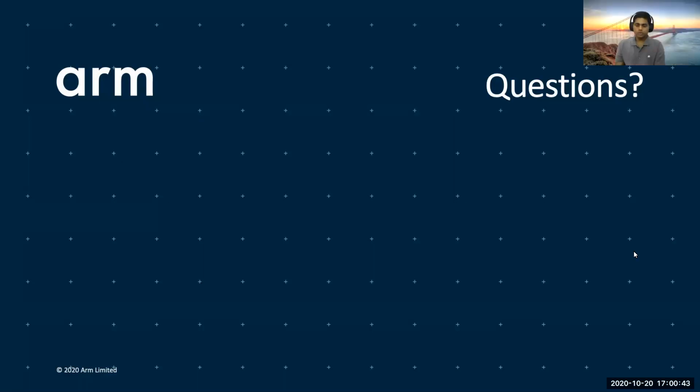Yeah, that's a good question. So how does mixed precision help in quantization when in hardware we only run 8 bits, right? When we are quantizing down to lower bit widths, the additional advantage that we get is we are saving the model size, or basically we are reducing the number of parameters. That helps in the bandwidth. That way, if a particular layer is bandwidth bound or weight bandwidth bound, you are basically speeding up the layer, although you are still running 8-bit arithmetic.